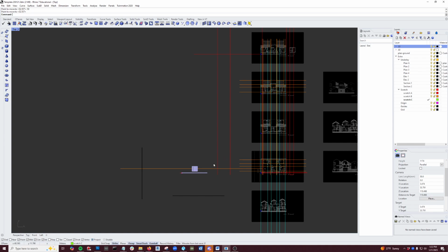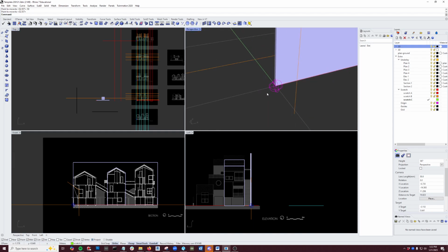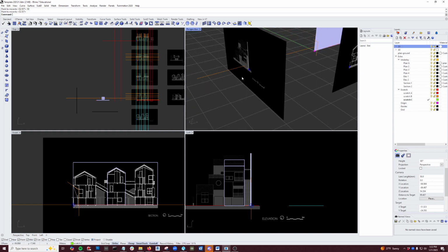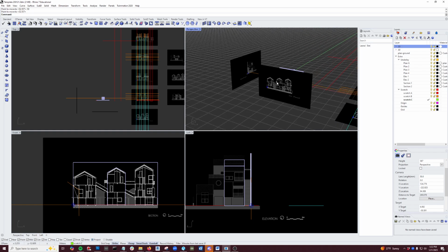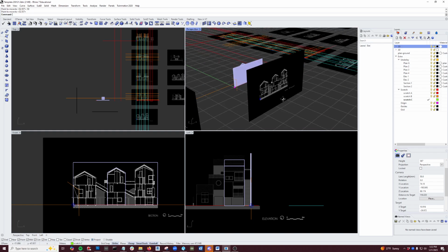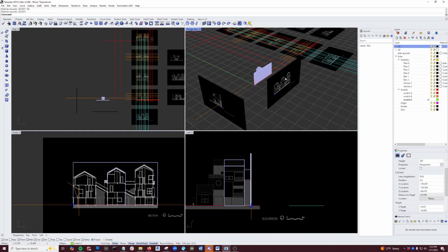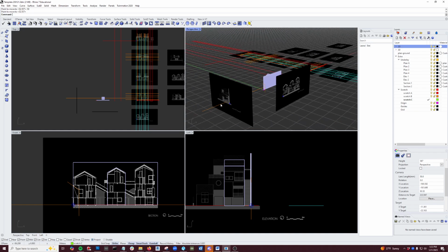And in addition to that, I've taken the sections, or at least one of the sections in one of the elevations, and I've oriented them spatially, in a way that lines up with the right orientation in 3D space. I flipped them up. I moved this one into a front view, and I changed this one from right to left on the screen. I made it a left view.